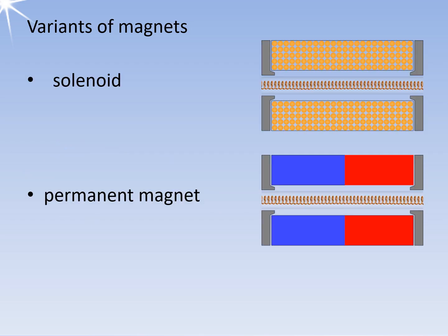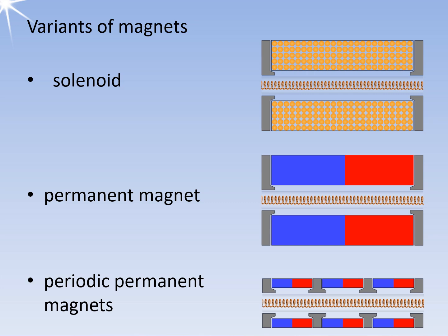A permanent magnet does not require a power supply and ensures that the magnetic field is always present. However, it does not allow for an adjustment of the strength of the magnetic field to optimize tube performance. If a single permanent magnet is replaced by several smaller magnets, the size and total weight of the magnet structure are reduced. The housing is typically made of aluminum to prevent the disruptive influence of ferromagnetic materials. External magnetic materials can interfere with the uniform magnetic field and damage the traveling wave tube. Therefore, the packaging of a traveling wave tube often has oversized dimensions.